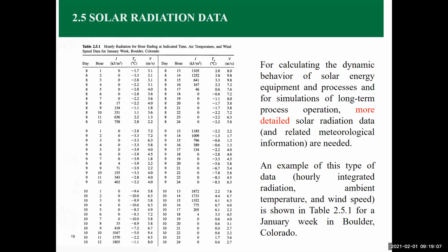So you should make sure when you are doing your calculations, for example, I need hot water for my house, then what type of solar collector should I buy, and how many solar collectors should I buy. That's mainly dependent on the weather conditions around you, and based on that, you can make your selection. You may have a day which is exceptionally cold, so that your solar collectors are not providing enough heat, but that's an exception.